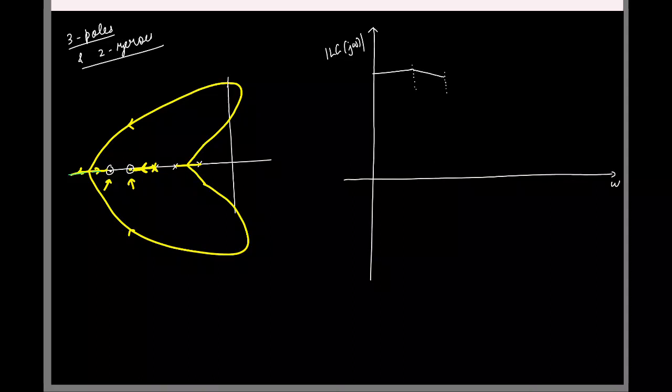It encounters the second pole, so does something like this. Third pole, minus 60 dB per decade. So let's say after some point it encounters the first 0, so then the slope increases, and then say one more 0, minus 20 dB. Let me extend this down.